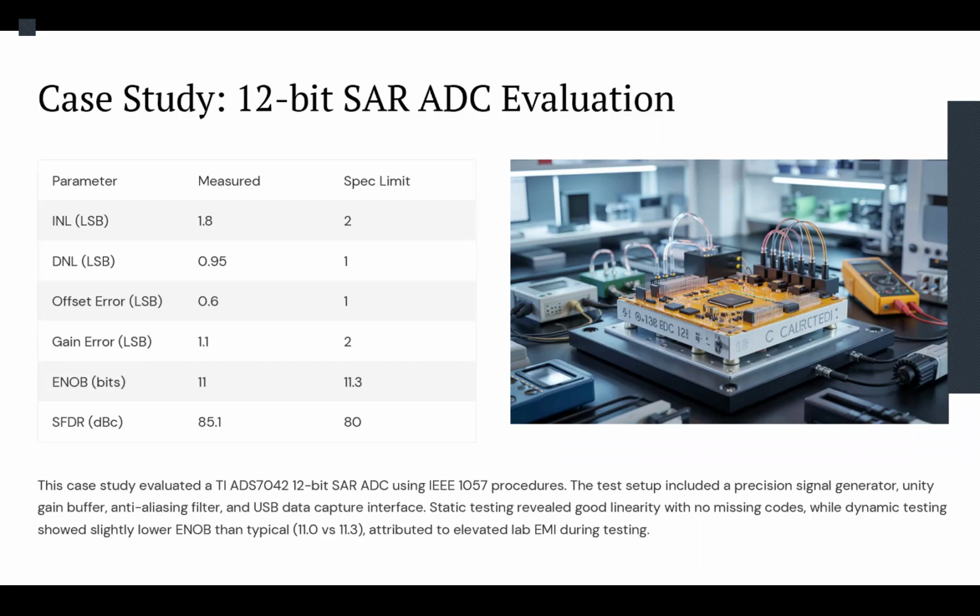We talked about how the root cause could be EMI in the lab, or USB noise, switching power supplies, or an unshielded laptop. After testing in a more isolated environment, we can actually improve this parameter.